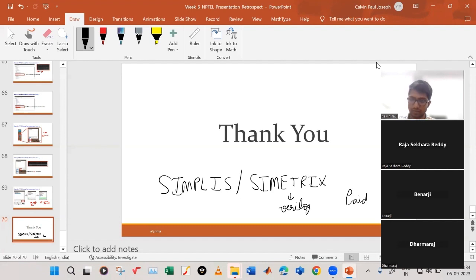Yes, sir. These DSOs and everything I can access. But this buck converter, they are having, sir, but we can't access those inductors, everything. See, in this board, we are using a small ready-made inductor. We're not using a custom inductor. So you could just use those readily available shielded inductors and make it. Capacitor also, sir, for the laboratory experiment they are using.